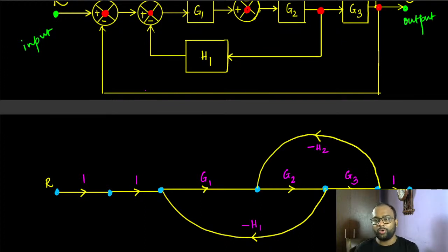Now say you want to send that signal to something that draws 1 ampere current. What will you do? You would put a transistor based amplifier that amplifies the signal in a way that the voltage does not change, but the additional current is taken care of.